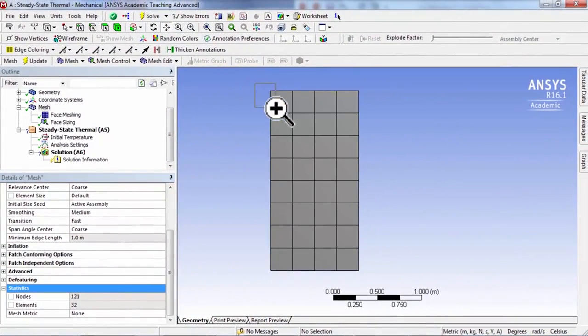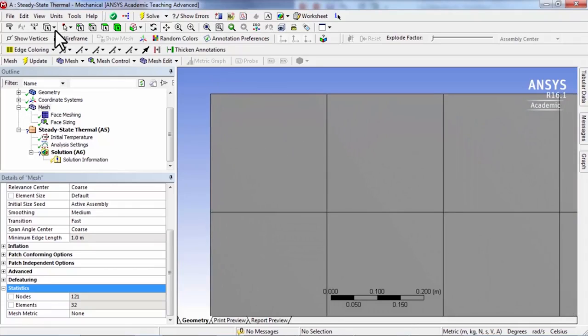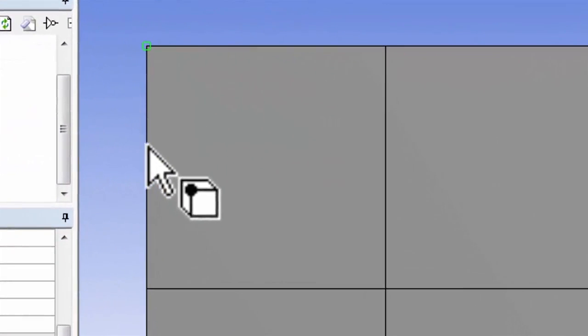Let me zoom in here using the right mouse button, and let me translate it. And I'll go here and I'll say select mesh. And make sure that the vertex option is on, so I can select elements, which will select this, or I can select the nodes using this option, and then I will just drag it over these locations.